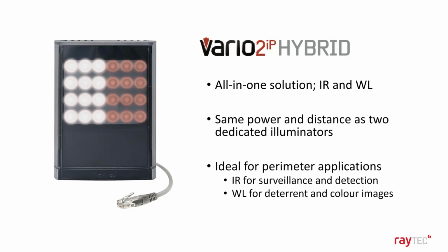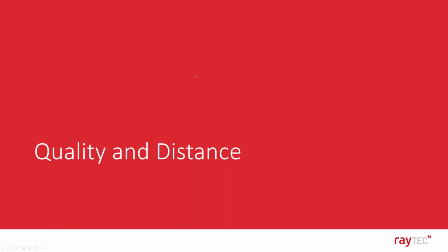So yeah, as mentioned, infrared and white light. A common use for this would be, you could have the infrared controlled by the photocell, so it would be monitoring that, and the camera would be monitoring the site in monochrome all night. And then what could happen is, you could have some other device trigger the white light to come on as a deterrent, all from the one unit.